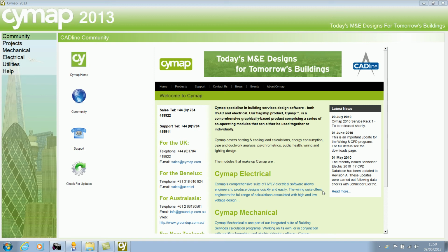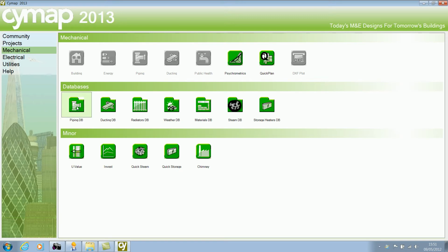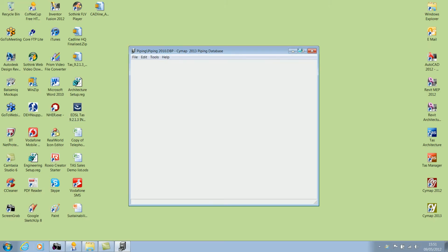This video will show you how to use the piping database and how to relate it to an existing project, or use it within a project. First of all, the database is in Mechanical, on the Mechanical tab, in the PIPEWORKDB section. The program will automatically open up the latest default database, Piping 2010. The piping database consists of constituent parts in the edit menu, namely pipe, pipe fittings, insulation, pipe medium, and selection rules.